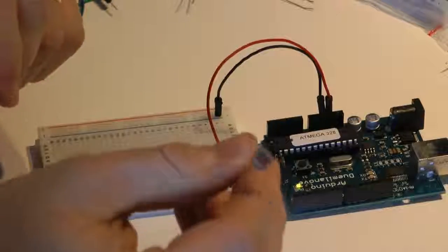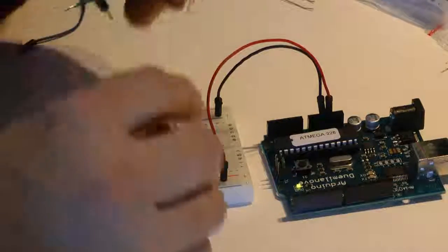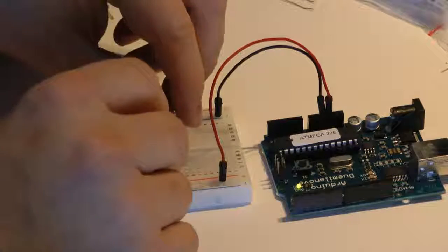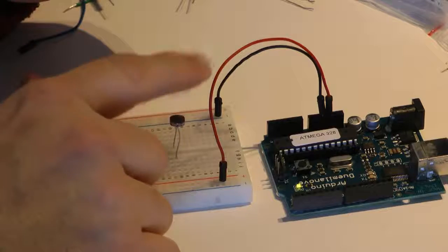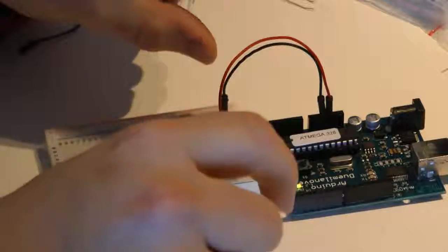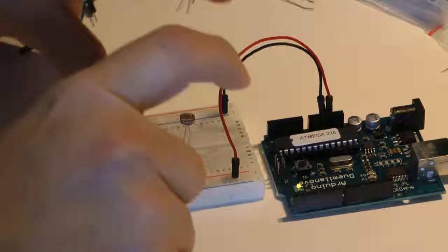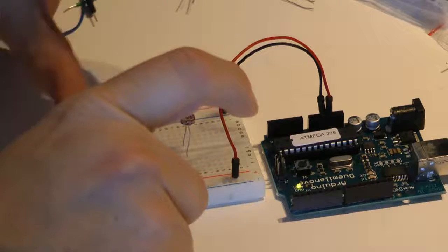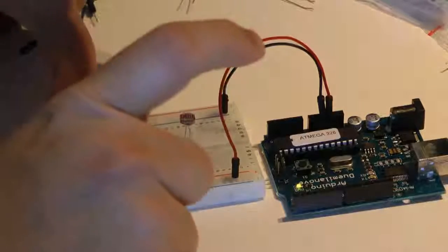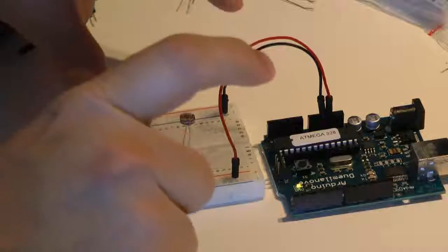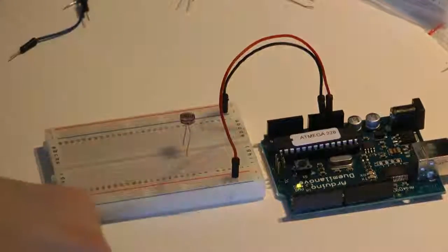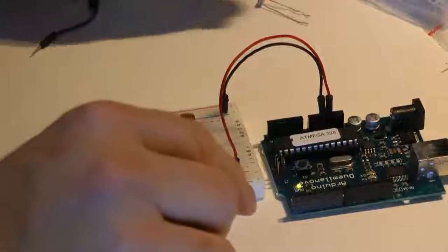The next thing we want to do is take our light sensor, which is our LDR. Now a sensor can be anything. As a water sensor for my plant at work that waters itself automatically, it's just two stainless steel screws. I have 5 volts going to one screw, and the screws aren't touching, they're just planted in the dirt. Then I have the other screw going to ground, and a sensor reading off of that to tell me what the moisture is. The more moist the soil is, the more electricity gets through. Voltage is what we're actually measuring.